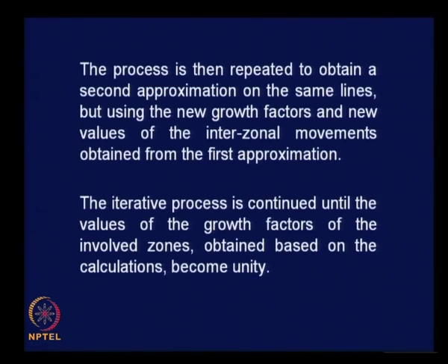I strongly advise all of you to continue this exercise and reach the point of convergence where the growth factors reach unity, and check whether you are able to get the expected matrix for the horizon condition. This is about Fratar's method of trip distribution,